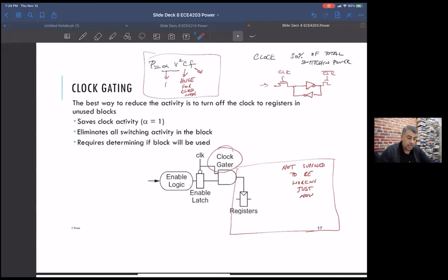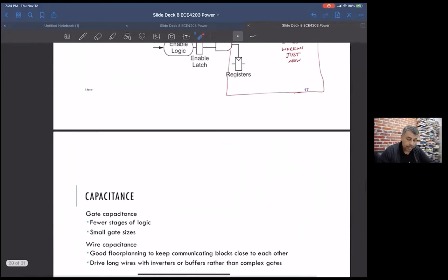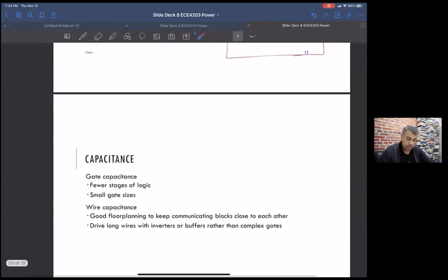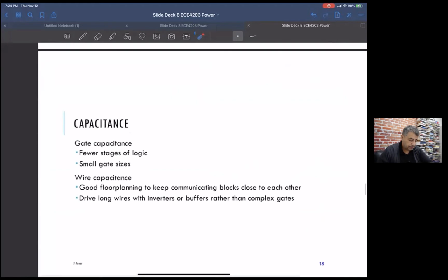But anyway, you cannot live without clock gating elements. This is a must-have to get a reasonable power consumption. All it's really doing is reducing the clock power consumption, but again, that's a big part of your power budget. Okay, so that's clock gating. So do it all the time, but be extremely careful, because you can really screw up.